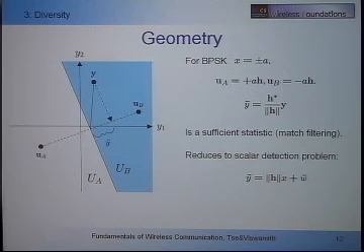All right. So now, let's go back to our diversity problem. If I do this projection, what is the end game? The end game is I set y equals hx plus w into this formula, and now I get y tilde to be equal to norm of h times x plus w. So the scalar detection problem that is reduced from the vector detection problem is the same as the scalar detection problem, except that the channel has changed from the scalar h to the norm of the whole vector h. Okay? So that's it. If you do the calculation, that's what you're going to get.